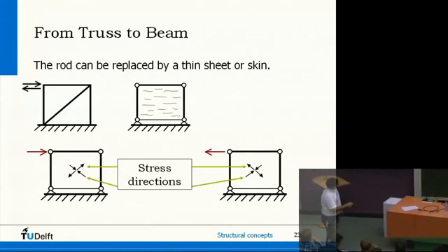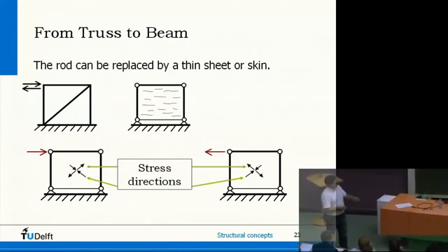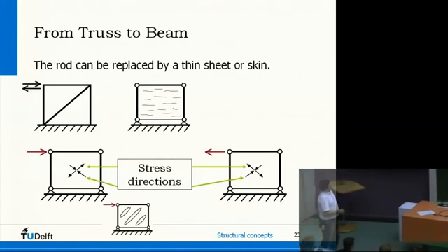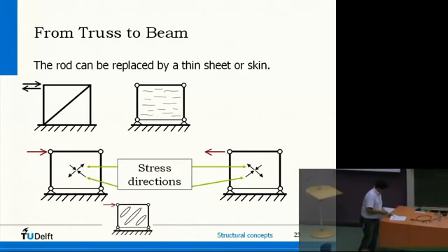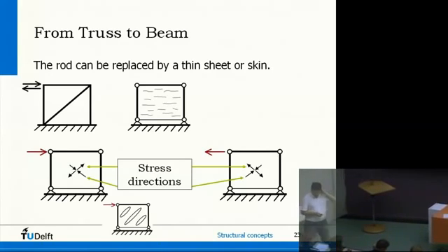In that case, you have here a sheet which is taking up tensile and compressive stresses. If we apply a load in that direction, the material wants to deform like this, wants to become longer in this direction, so I have a tensile force in this direction. In this direction, it tends to become shorter, so I will have some compressive forces. So if I have this load, sometimes you see these type of wrinkles appearing. And that means elongation in this direction, contraction in that direction. Later on I will show you a nice picture of that. Okay, so far something about one cell.